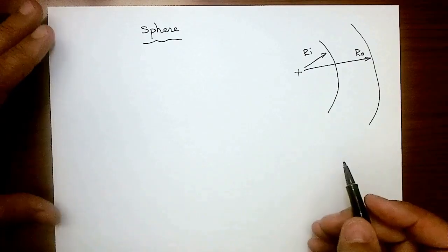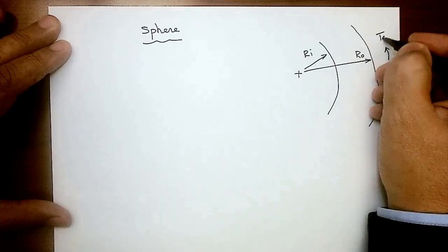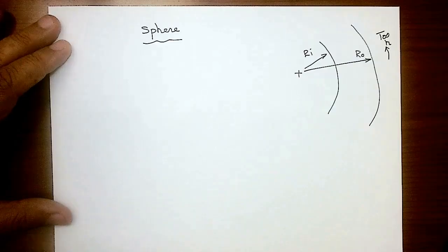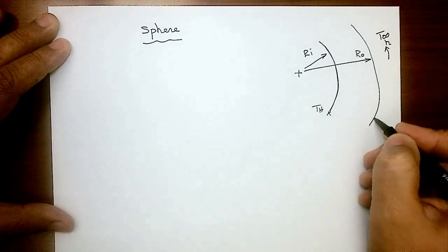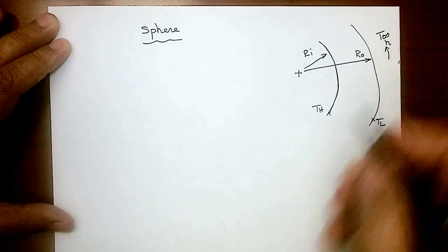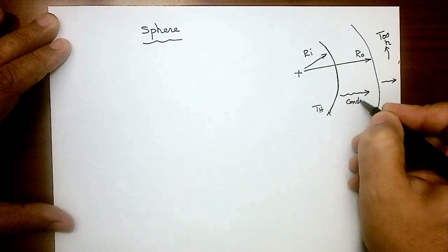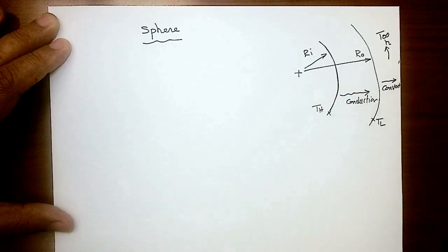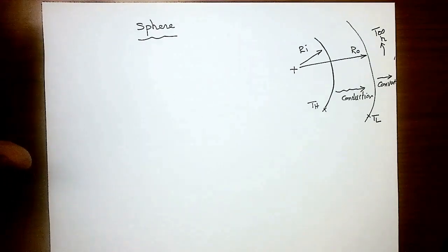So basically, the sphere will maybe be exposed outside to a fluid, but there is nothing inside here. Okay, so let's assume that the inner surface here is at a very high temperature, TH. The outer surface is TL, and there is a convection outside. So I know that there will be a conduction going here, and there is a convection going here. That's conduction. That's convection. No internal heat generation inside the sphere. It's a steady state problem. So what's in is what's out.